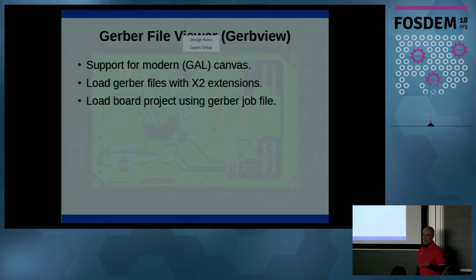They will load with the Gerber X2 extensions, and there's also work currently underway by the Gerber folks to come up with a new file called a job file format, which is basically a definition of your entire board: the stack up, all the different layers, how they're stacked up, the widths, the distances between each layer. There's what's called a project or job file, which you can send to your board house, assuming they support that. So you don't have to tell them the layer stack up and everything.